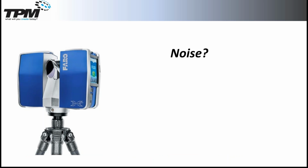Noise. This is always a question that comes up. It's not hard to recognize that if someone walks in front of your scanner while the scanner is operating, that's probably going to cause problems. And problems is probably too serious of a word for it. Simply because it's a line-of-sight instrument, if someone gets in the way, they're then going to be measuring the points on that person or that car or that dog or whatever is in the line of sight. And generally, it's only a problem if someone or something stands in the way for an extended period of time, because then you're actually blocking your area of interest.